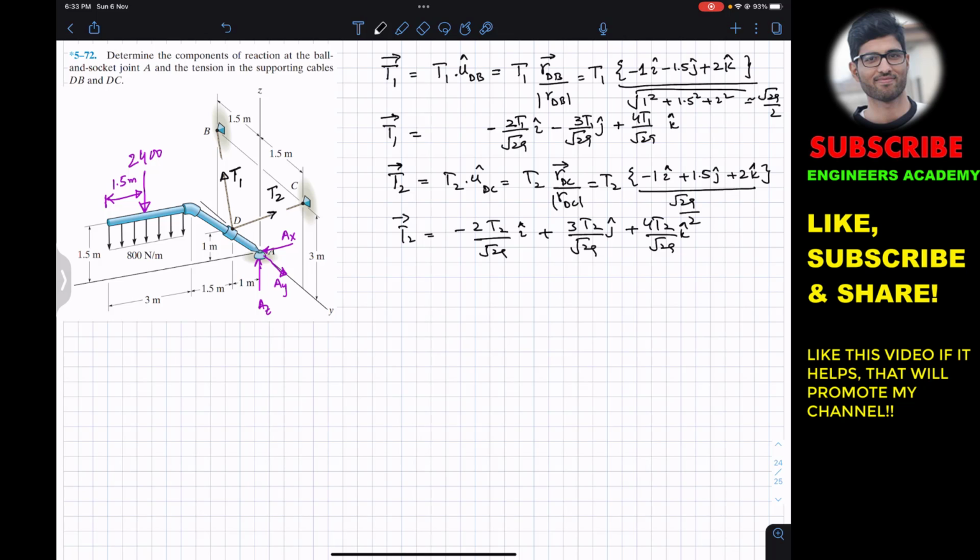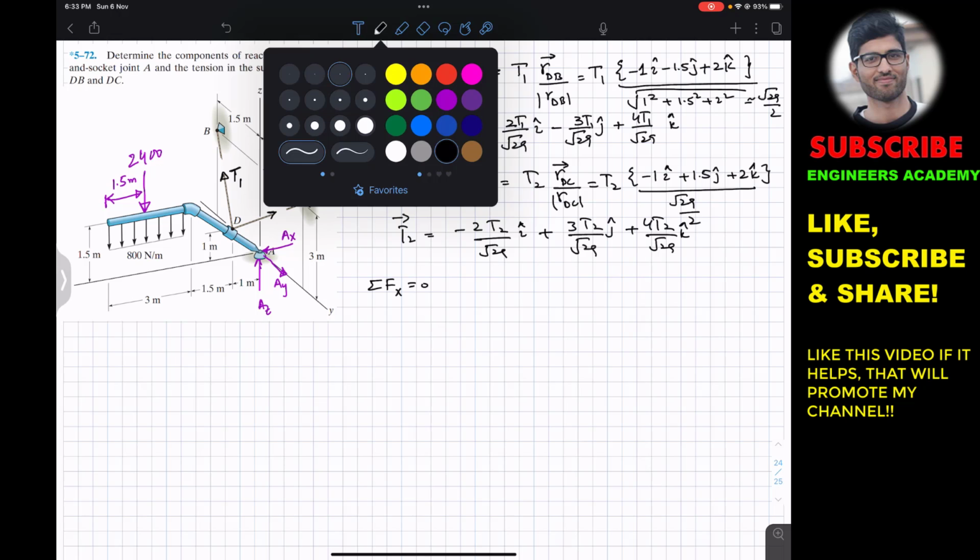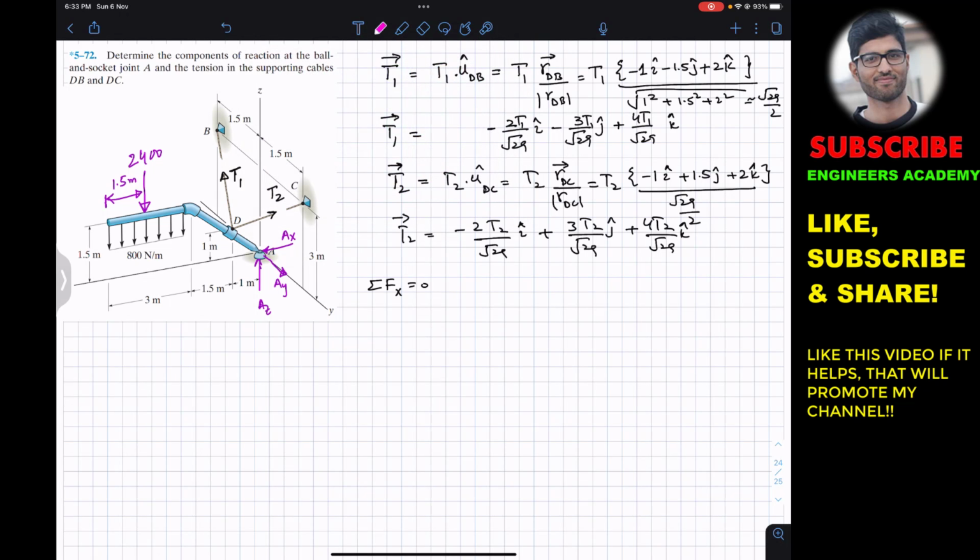So now if I apply the summation of forces along x, that must be equal to 0. So first of all, let me represent the components of t1. So t1 has one component in the negative x. So this is in the negative x. Similarly, t1 will have one component in the negative y, and it will have one component in the positive z. So this one is t1x, this one is t1y, and this one is t1z.